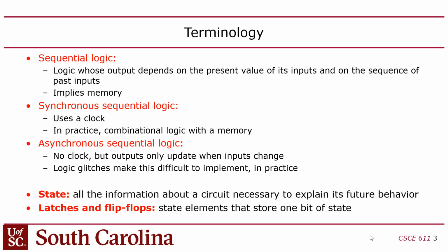So sequential logic is a broad term that describes logic whose output depends on past inputs, but sequential logic doesn't necessarily need to involve a clock. You could just have a case where you have cross-coupled gates, or logic gates with feedback. That's the way you can implement a latch, if you've ever seen a latch designed with cross-coupled gates.